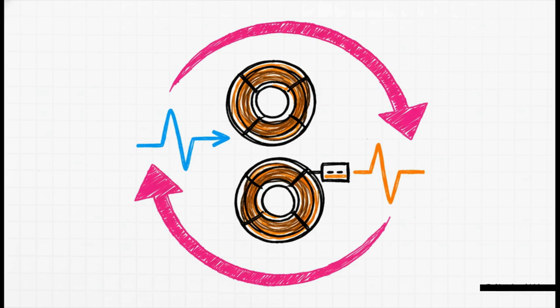You feed the main power to one set of coils in the motor, and you feed this delayed power from the capacitor to a second set of coils. And just like that, you've created a fake rotating magnetic field. It's not a true one, but it's enough of a nudge to get the motor spinning.